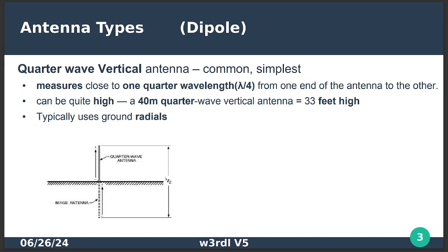The thing that I did for all of these parts on a technician test, I just looked at the band. So if it says it's a 40-meter band and it wants to get a quarter wavelength, then you already know a quarter wavelength is going to be 10 meters. You already know 10 meters is roughly 33 feet, and there's your answer. Now, it may ask for the answer in inches, and then you'd have a little more calculation to do, but that's fairly simple. So, howdy, David.